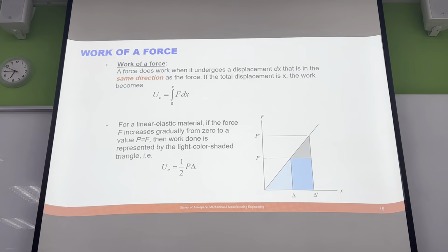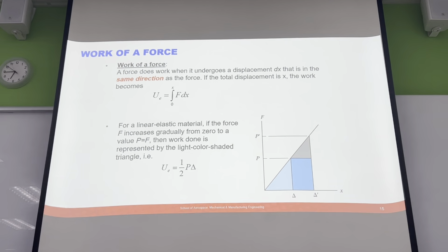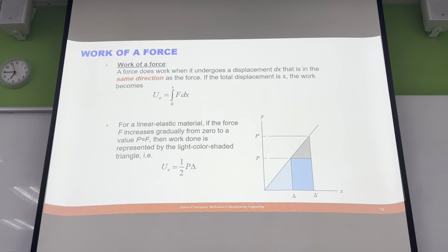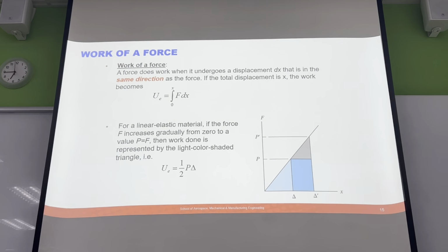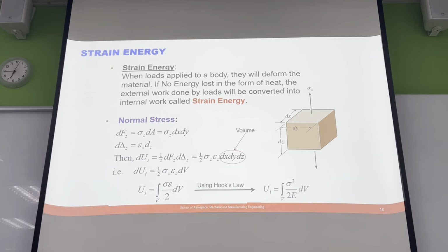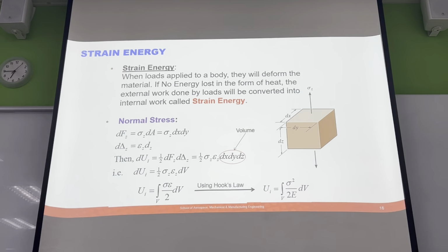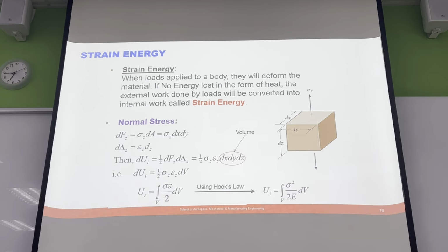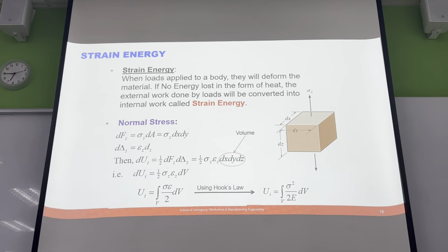Here we have force times displacement, but you can also have moment times rotation, and that has to be at the same location. And we're equating those two things. If we can come up with an equation which tells us what stretch you're getting due to that loading, whether it's a force or a moment, throughout the whole volume, you can just put it in there.